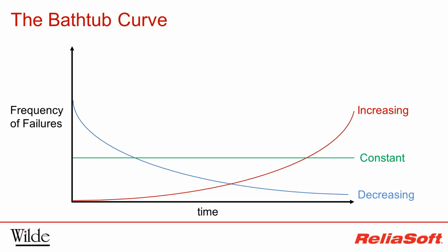Where damage is accumulating and scheduled maintenance can be effective, these failures will typically occur due to weak design, wear, installation breakdown, fatigue, and corrosion. Overlaying these modes gives us the recognisable bathtub shape. Although the scale of each region very rarely matches the one shown, the overall trend is consistent.